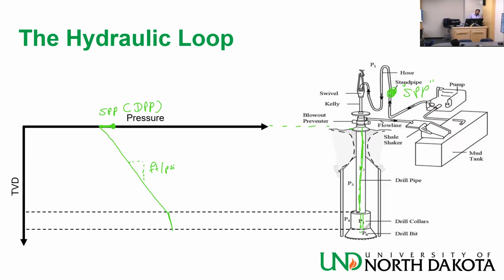But do I lose pressure or gain pressure? You don't know it yet, but the way you see it, on the surface I lost pressure. Then downhole, I gain pressure, net. I gained and lost, but net was gain. And then in the drill collars, I gained and lost, net was gain. And now I'm at the bit, I'm only going to lose, if I ignore the height of the bit.